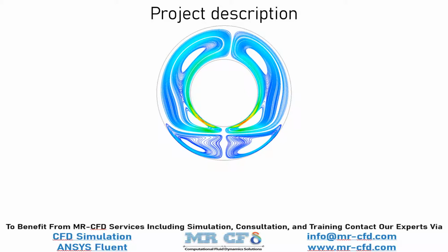The energy equation is activated to obtain temperature distribution inside the computational domain, and the laminar model is exploited to solve the fluid flow equation. The solidification or melting model has been used to analyze the phase change of PCM material from solid to liquid and vice versa due to the temperature change inside the water storage area. You should apply the Boussinesq model to determine the density changes in proportion to temperature.